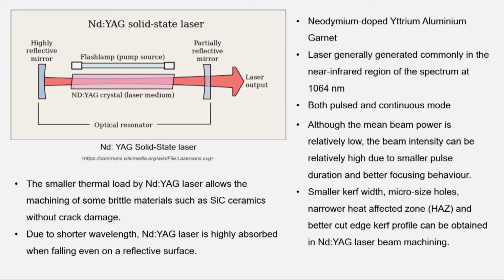The acronym Nd:YAG stands for neodymium doped yttrium aluminum garnet. Here, the element neodymium has been doped into yttrium aluminum garnet, and this solid is used to generate the laser beam in manufacturing operations. This laser falls into the near infrared region and provides a wavelength of about 1064 nanometers. This laser is also used in both forms, that is pulse mode and continuous mode.